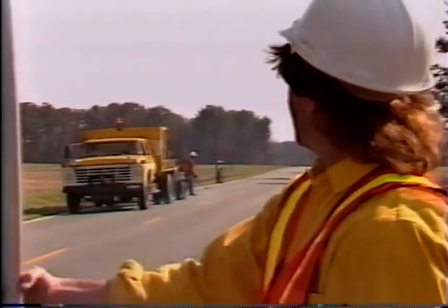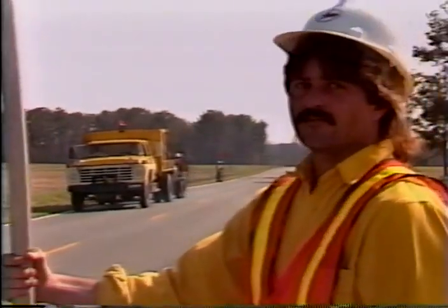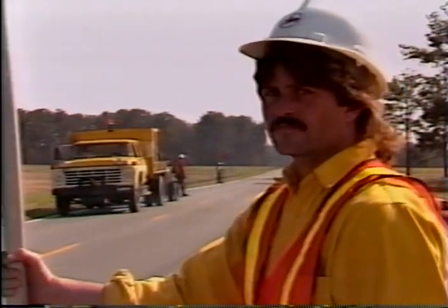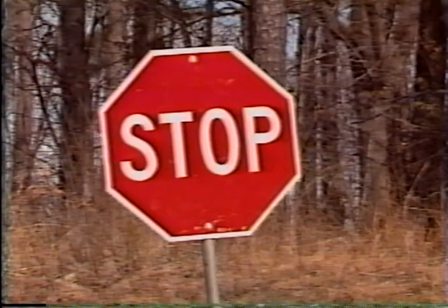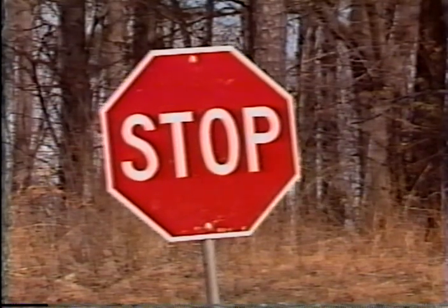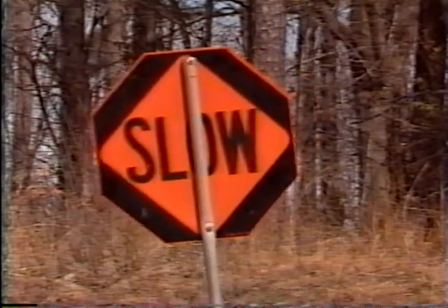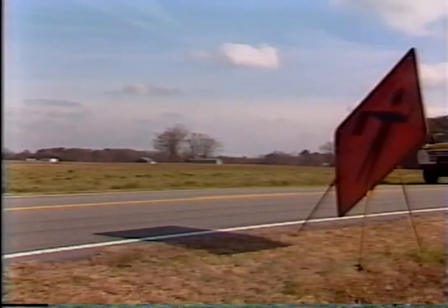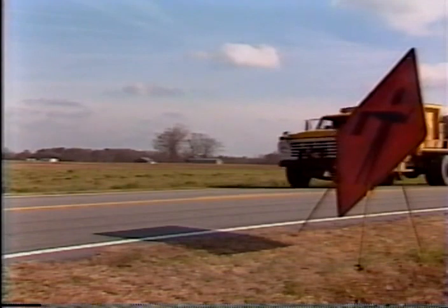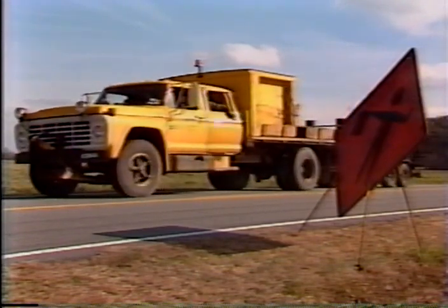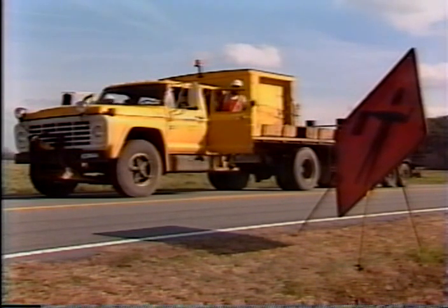On occasion, a third flagman may be required due to poor sight distance or intersections. Use a stop-slow paddle in all maintenance activities. Flags should only be used in emergency situations. When the operation approaches the end of the extended work zone, suspend work until the signs are moved.